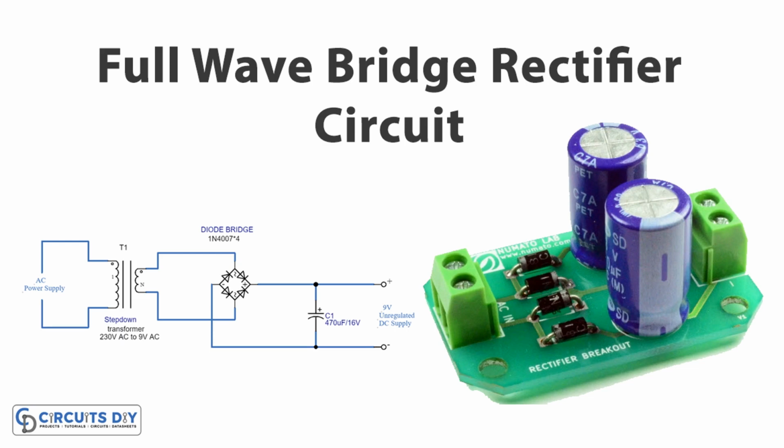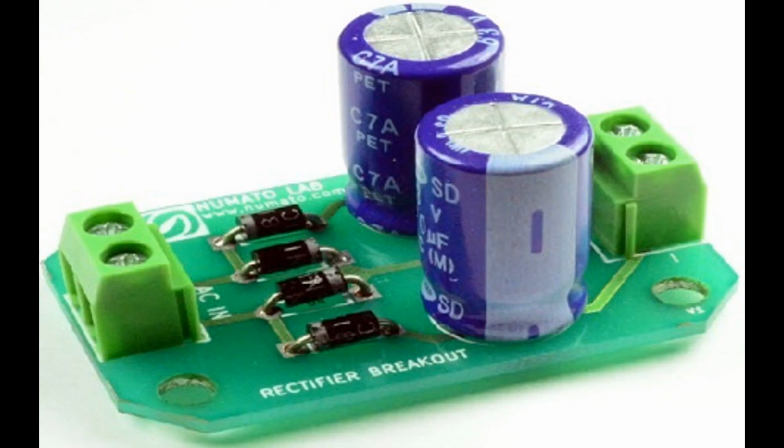Full wave rectification. Bridge rectifiers provide full wave rectification, ensuring that both the positive and negative halves of the AC waveform are converted into DC. This results in a more efficient charging process compared to half-wave rectification, where only one half of the AC waveform is utilized. Constant voltage charging. Many battery chargers employ constant voltage charging, where the charger maintains a relatively constant DC output voltage across the battery terminals during the charging process. The bridge rectifier, along with voltage regulation circuitry, helps achieve this by providing a stable DC voltage to the battery.